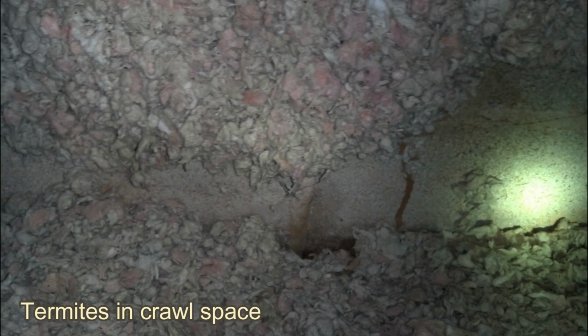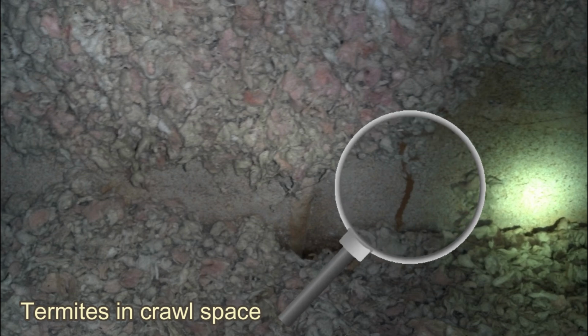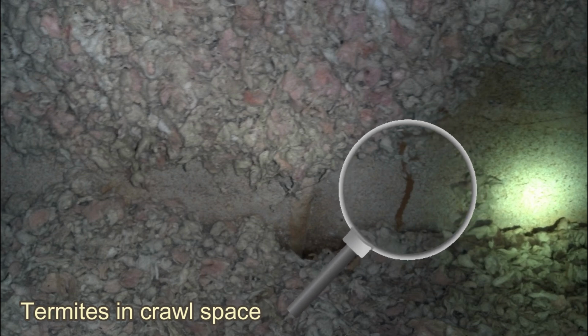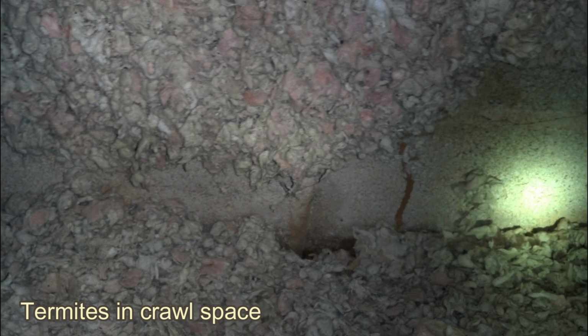In the instance you can see on the screen, we found termites in a crawl space. This was really tricky because the crawl space had blown-on cellulose insulation on the walls, and we actually had to remove it to do a termite inspection. At least we had to move a few inches of it, as you can see, and that's how we found the termites. But it would have been really easy to miss these termites. And when we talk about IPM, identification and finding the problem are some of the biggest things, so sometimes you have to remove obstacles to be able to get to where you want to see.